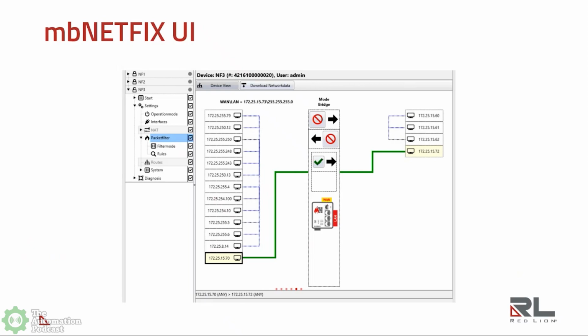And then again, it puts control at the end there. So whoever the operator is that needs the controls engineer to connect in, he presses the button, turns the key, or whatever he needs to do to allow that conversation to happen. And then once he's done, he shuts it off. Yeah, and if you have a bit in the PLC that tells you whether you're in production or not, you can use that. There you go. When the operator takes the machine out of production, it opens it up for the engineering guy in the office to come in and take a look and see what's going on.